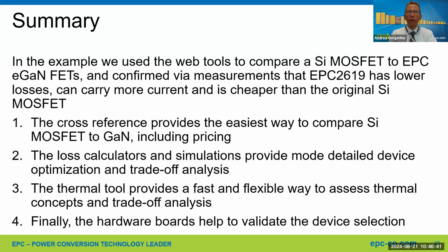What we do offer is an example of a reference design using a multi-level topology. That's very common. It's an approach to do the same thing as putting FETs in series, but do it at the level of the topology, not at the level of the device. So we have an implementation for the DC-DC converter with 3 levels. We also have a PFC with 4 levels, and all of those showcase how you can do exactly what you said, but at the topology level.